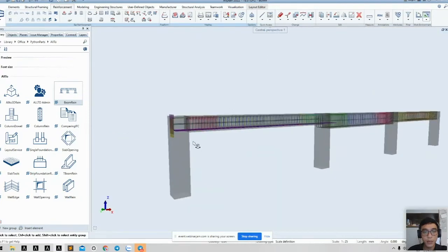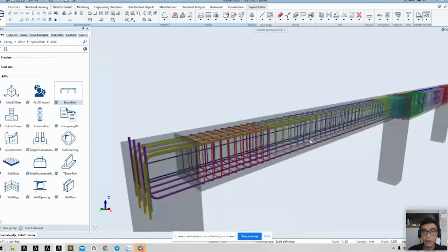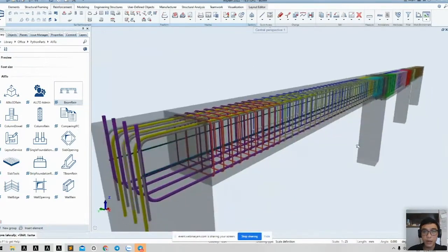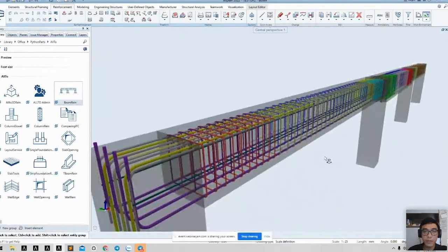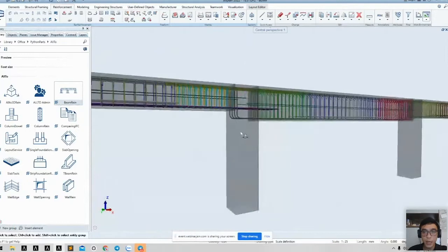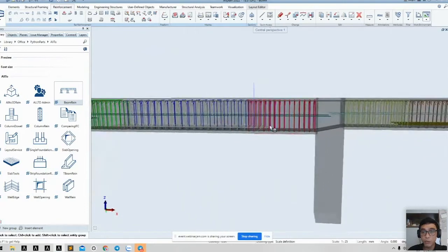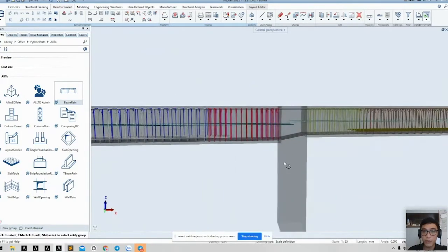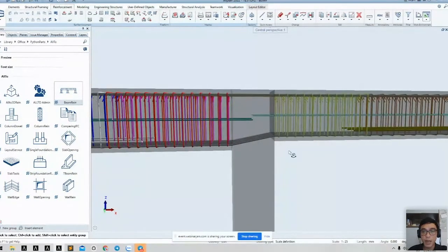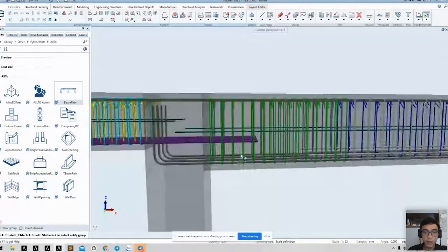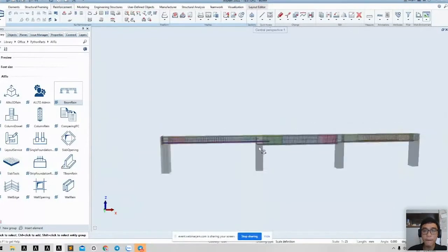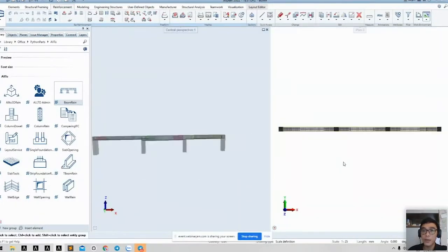So as you can see here, we have all types of rebar for the beam reinforcement. With the condition, we can set the tool to automatically create the bottom or the top rebar, ground here, or stop and lap here. And finally, I will show you how to use the wall reinforcement Python part.